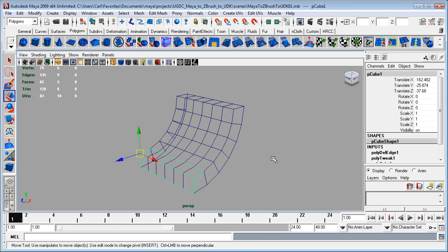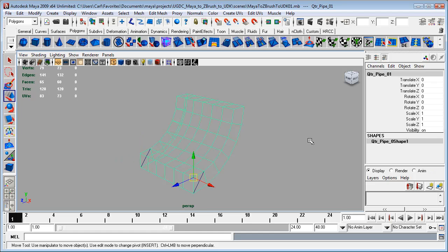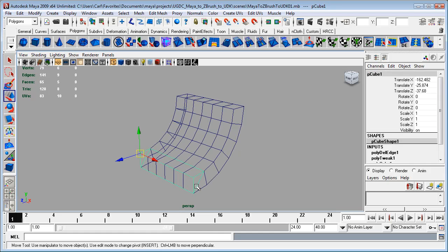And just to save time, I'm going to rename this collision mesh now. I'm going to select our main object, click on the name, copy the name, come down to this collision mesh, click on its name, and paste the main mesh name in its name.